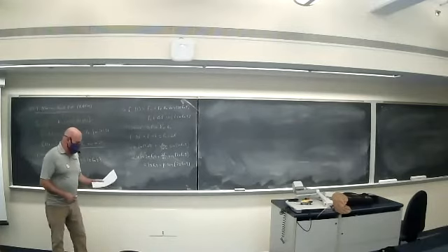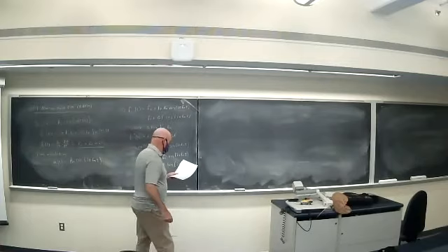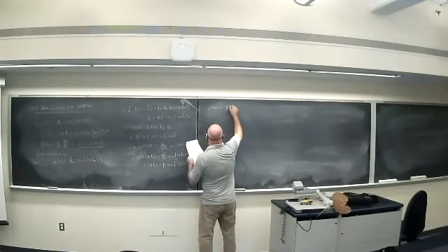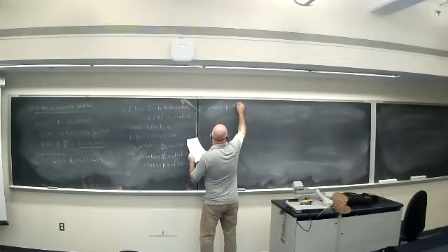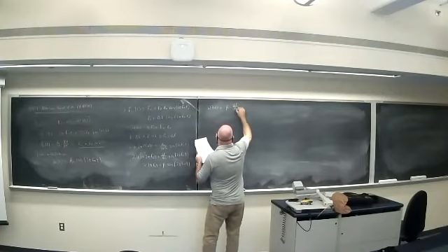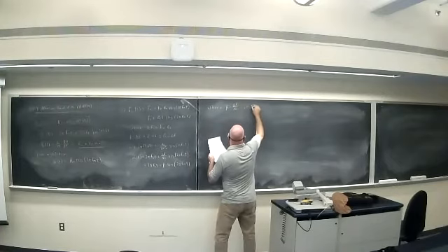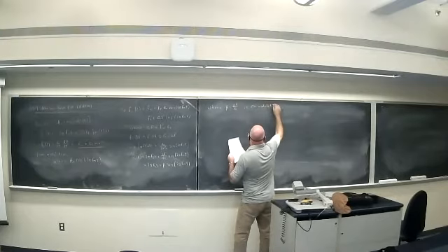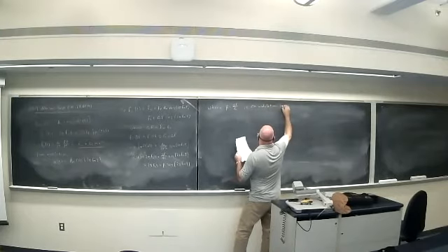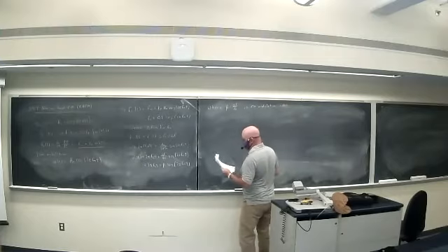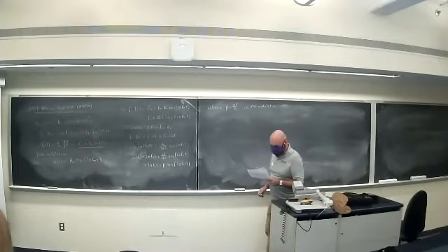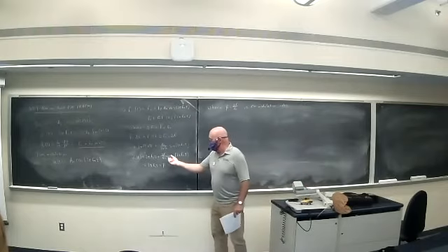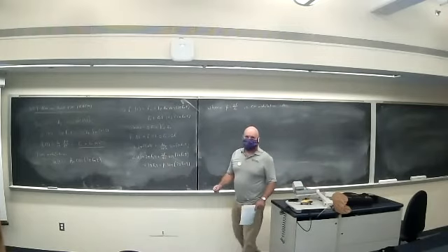And so just for notational convenience, that's defined as beta, where beta is delta F over FM. And this is what's actually called the FM modulation index. It's the ratio of the peak frequency deviation to the tone frequency.